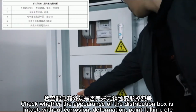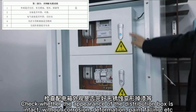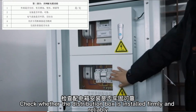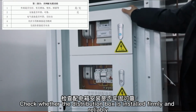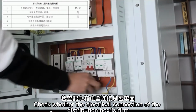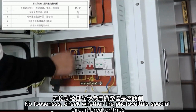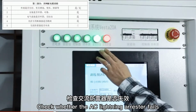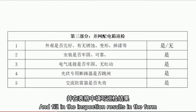Check whether the appearance of the distribution box is intact, without corrosion, deformation, paint falling, etc. Check whether the distribution box is installed firmly and reliably. Check whether the electrical connection of the distribution box is firm, with no looseness. Check whether the photovoltaic special circuit breaker trips. Check whether the AC lightning arrestor fails, and fill in the inspection results in the form.